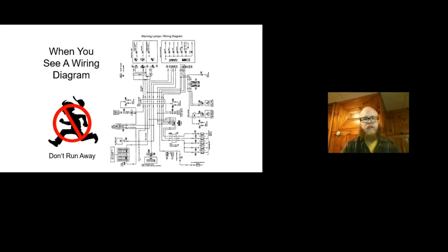The nice thing about these map diagrams is oftentimes they'll show images of the connectors right there on the diagram, so you don't have to look up the connector view to figure out which terminal in that connector is the one that you want. The troubling thing is you're kind of overwhelmed with all the information. There's a little bit more shown to you than what you really want to see, at least for me.